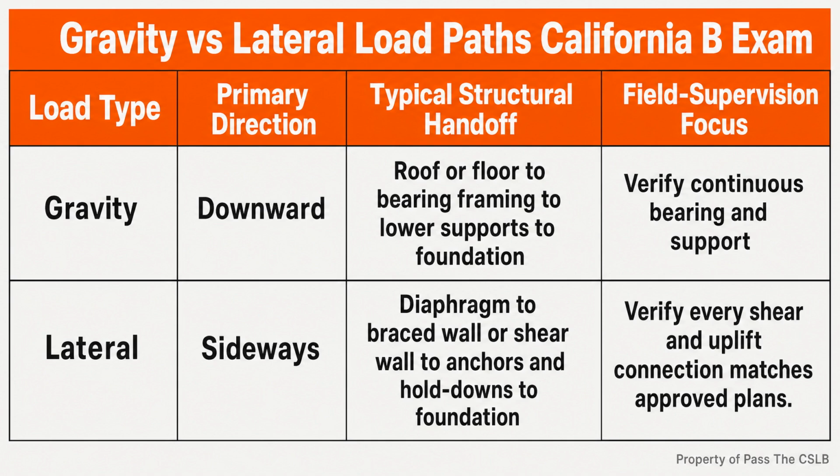A heavy shear panel, a large hold down, and a strong concrete footing do not rescue a missing connection between them. The system is only continuous when every handoff is present, correctly located, correctly fastened, and installed as the approved plans require. Imagine a contractor looking at a framed wall that appears exceptionally solid.